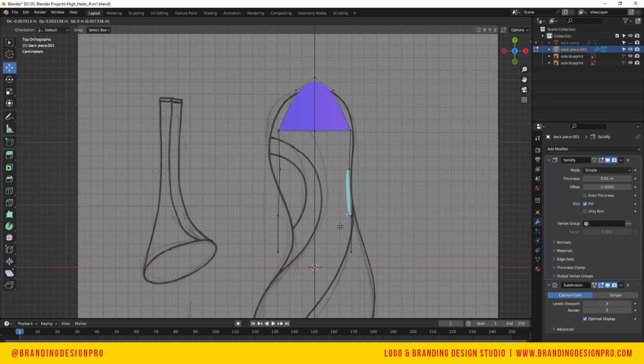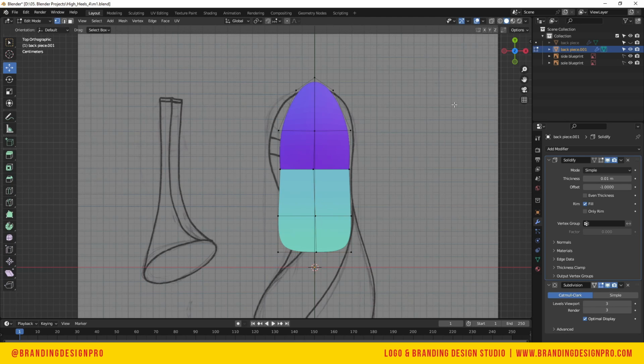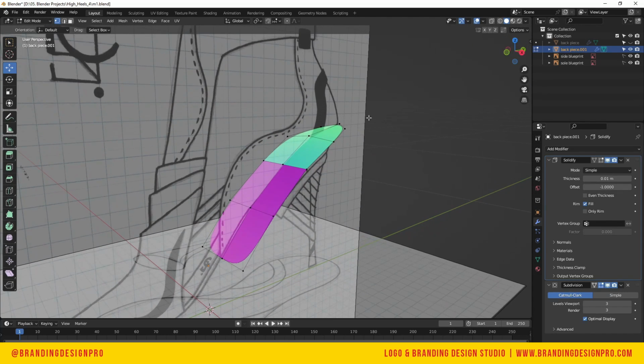So now we're going to create those 2 new vertices inside. Then select the 4 vertices, fill, 4, fill, and then these last 4 and fill. And then select that last vertice, extrude, and then you know what to do, fill. Select these 4 and fill. So far this is what it's looking like. We didn't really have to adjust the placement or the movement of the vertices.